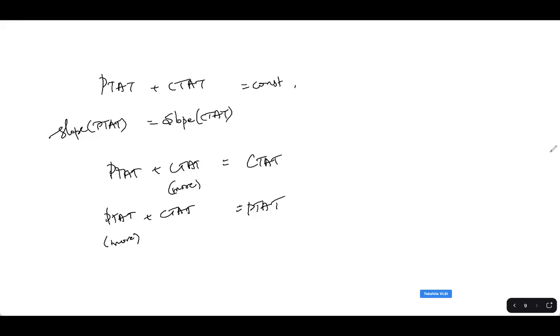Let's come back to the basic concept. Somewhere in some device you must have found something that's very much PTAT in nature or very much CTAT in nature. What is that particular thing that we have found? If you look at BJTs, bipolar junction transistors, or even diodes for that matter, the diode or BJT's junction voltages.